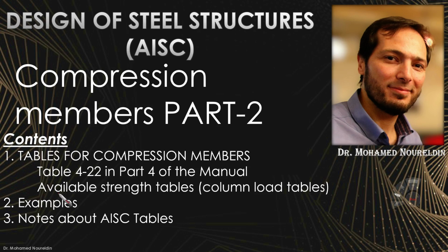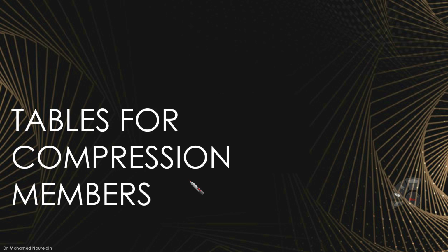On top of that, I'm going to talk about the available strength tables, or commonly we call them column load tables. And after that, I'm going to give a couple of examples, and then I'm going to wrap up with some notes about AISC tables in general. Okay, let's jump into the tables directly and see how we can understand them in general and how we can use them in our design.